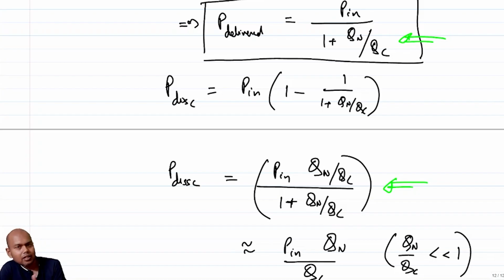But having said that, given the plethora of options that you have, you'll have to choose the ones which have lower component Q. Now, the point that I was trying to make, while I made that incorrect statement, was that if you have single L and single C networks like the ones that we have talked about till now, then the Q factor is essentially also the impedance transformation ratio, right?